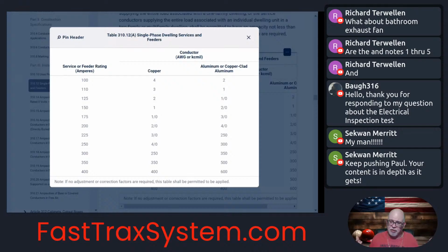And you're usually never going to have more than 3 current carrying conductors for a typical service, especially a residence. So that usually doesn't come into play. But the ambient could come into play, but ironically, I just don't see many people taking it into account, but you're supposed to. On an exam, it could come into play. So be aware of that.